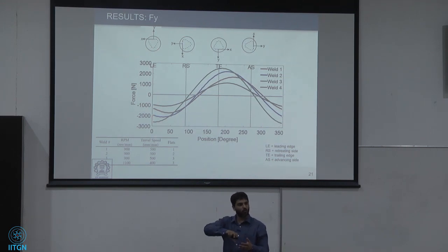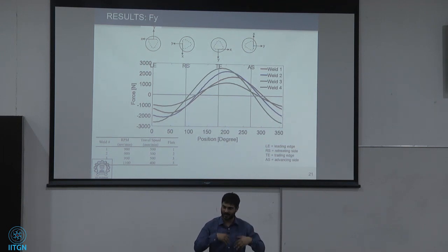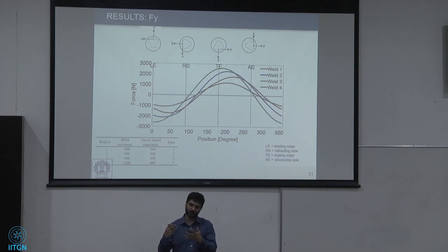As the material moves around the tool, these compressive forces relax down. Again, at the end you see there is a lot of rise in the tensile forces, or by tensile forces I mean the forces have changed signature. They have gone from compressive negative to a positive, which should correspond to tensile here, which is very interesting.